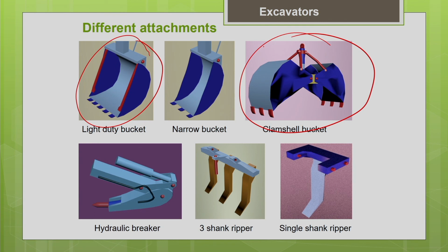I can use it for trenching or excavation of material from a manhole or sewer, or for excavation from a pier foundation. So, wherever I need some vertical digging, I can use this clamshell arrangement. This is also a very popular attachment, and as I told you, it can even be mounted on cranes.